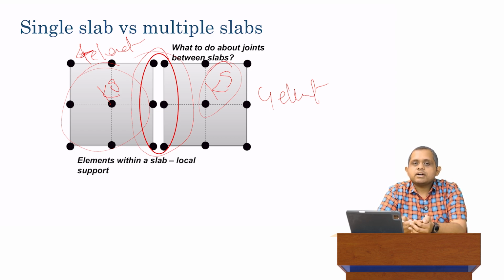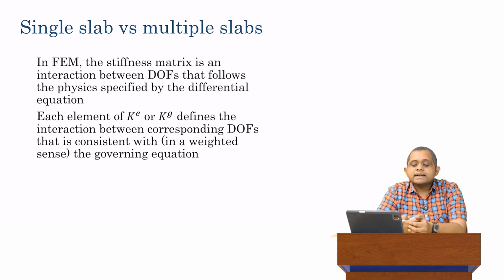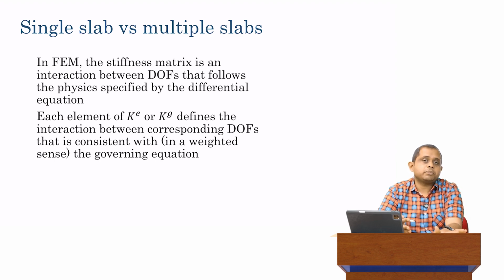That is a question that we have to deeply consider. Analytically doing it is actually quite difficult. As I said before, Freiberg theory is essentially uncoupling these two. The dowels are analyzed separately, the slabs are analyzed separately. We are not doing an integrated analysis of slabs and dowels. And that's a significant shortcoming in the analytical methods.